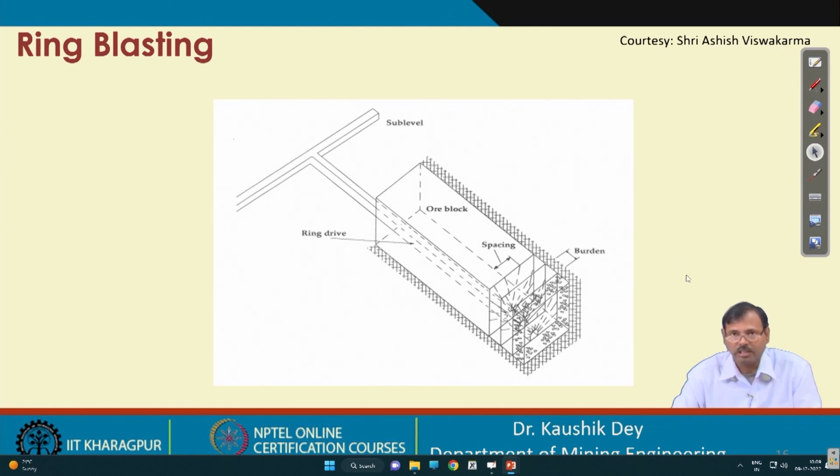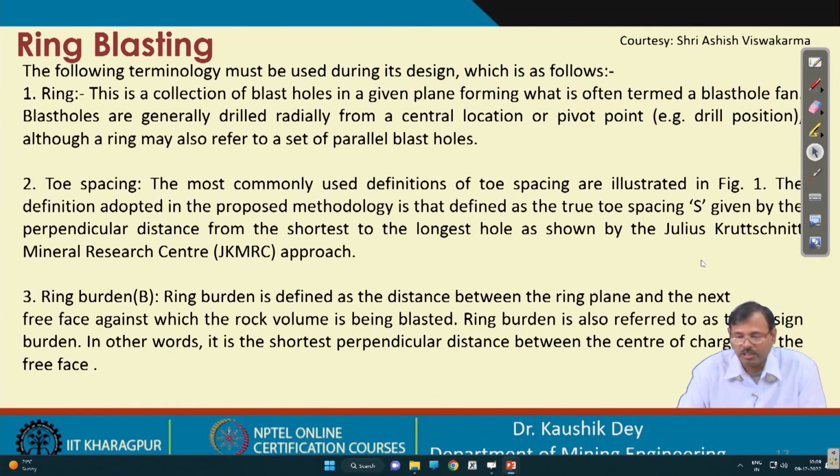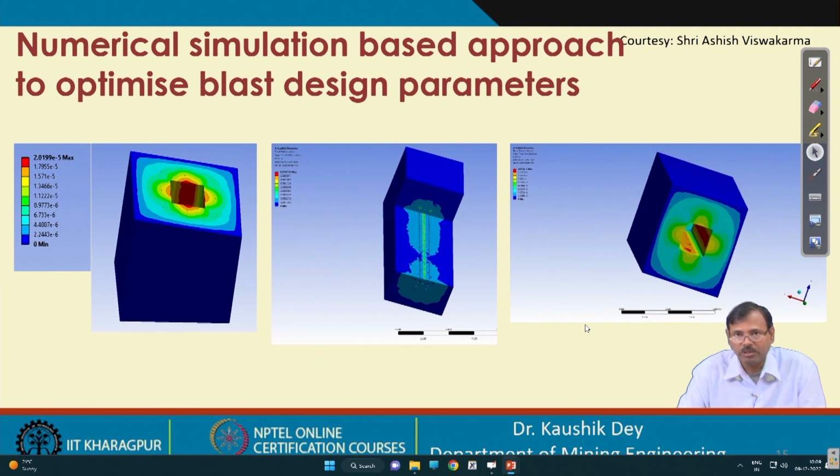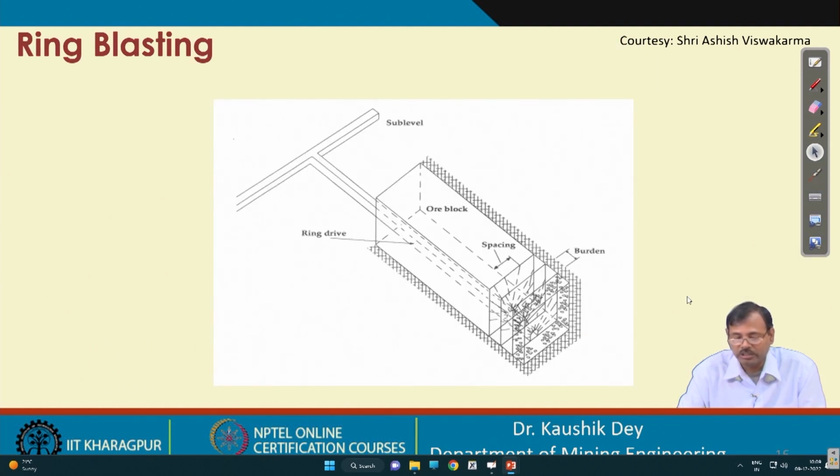but anyway that gives you a prior idea before the blasting, you can understand, and based on that you can change the charge positioning, especially the spatial distribution of the charge can be carried out there. So, in fact, the positioning, that is the charging, how the charge has to be made, whether deck charging should be there or not, all these decisions, what should be the amount of stemming, that can be easily simulated in this numerical analysis software.